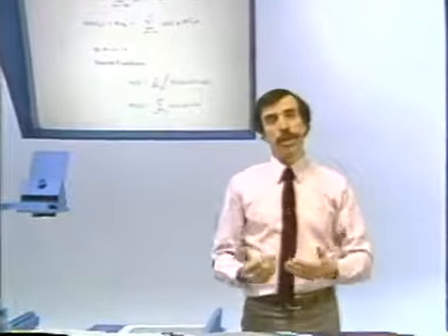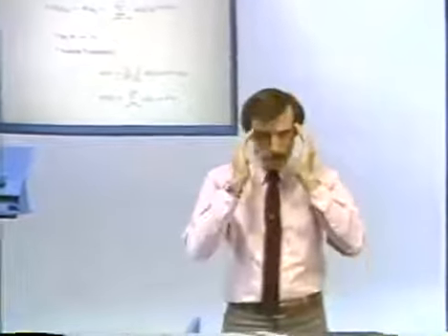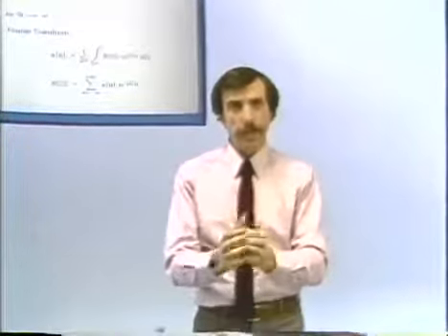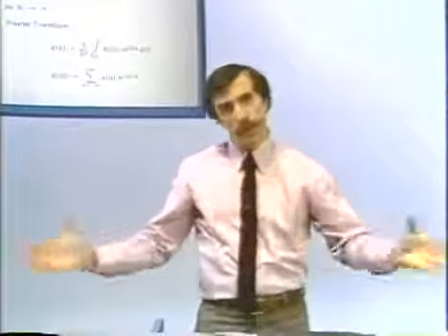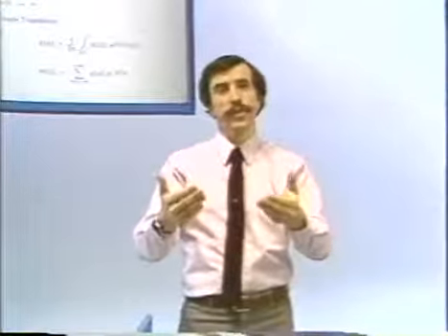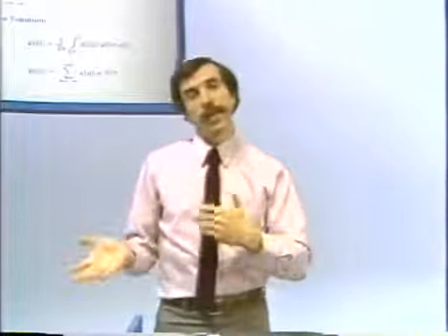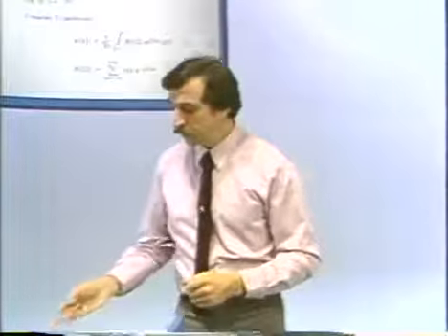So, although there is a little bit of mathematical subtlety to be tracked through in detail, the important conceptual thing to think about is this notion that we take the aperiodic signal, form a periodic signal, let the period go off to infinity, in which case the Fourier series coefficients become this envelope function, and incidentally, mathematically, one of the sums ends up going to an integral.